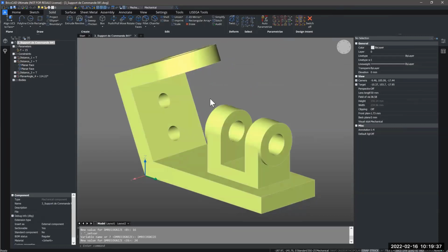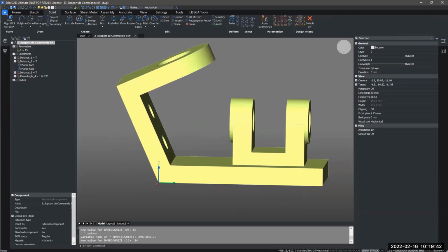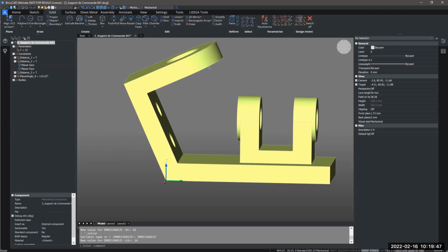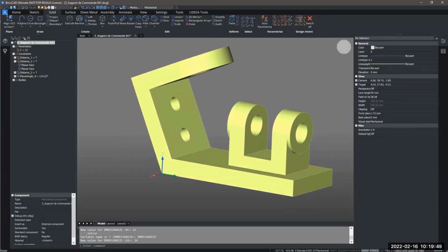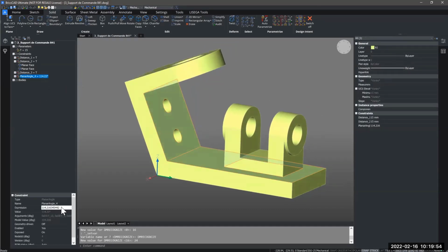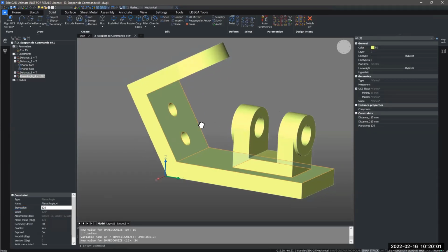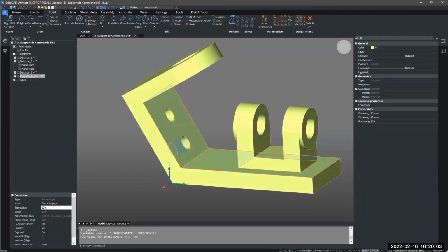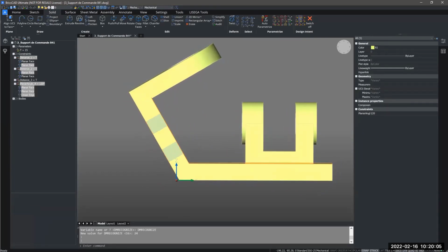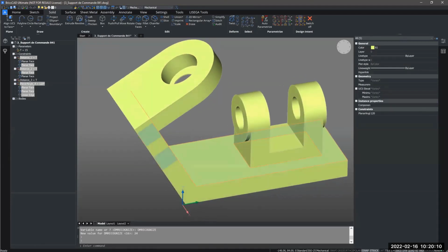You saw earlier that the top part here also stayed in place when I changed the angle. So with these changes, it should now stay connected here. And the relationship between the geometries should stay intact. So I will change the value once more to 120 for the angle. And you can see the entire feature moved. The holes should now be perpendicular to the surface, which it looks like they are. Same for the top here.